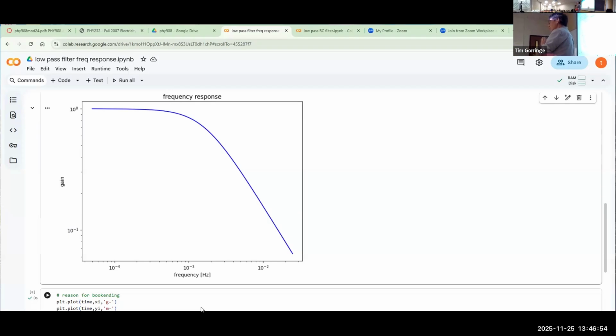One thing about low pass and high pass filters: they are very effective in having a gain of one and smoothly passing the signal, or having a complete extinction of the signal, if the signals you want are separated by a lot from the signals you don't want. So if you have high frequency noise and low frequency signal, or vice versa, then high and low pass filters are great. What they're deficient in, and you see it here, is the transition region from passing the signal to extinguishing the signal, if you want to select signal from noise across a broad range of frequencies.